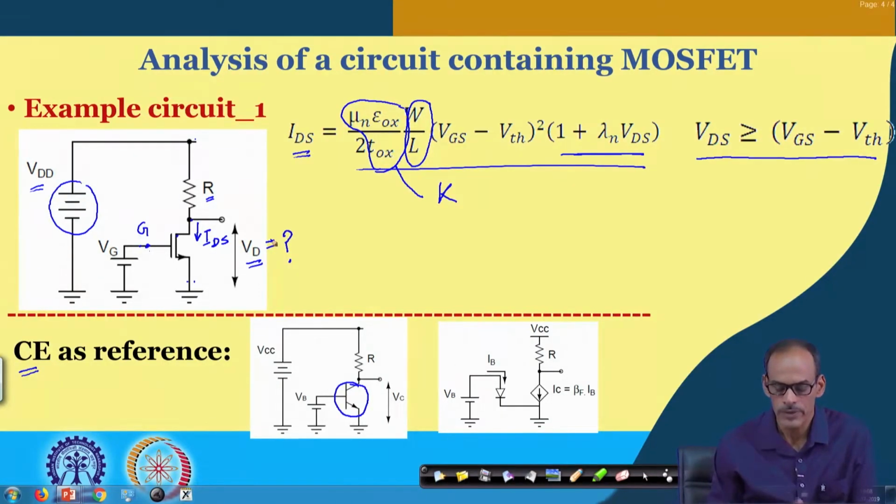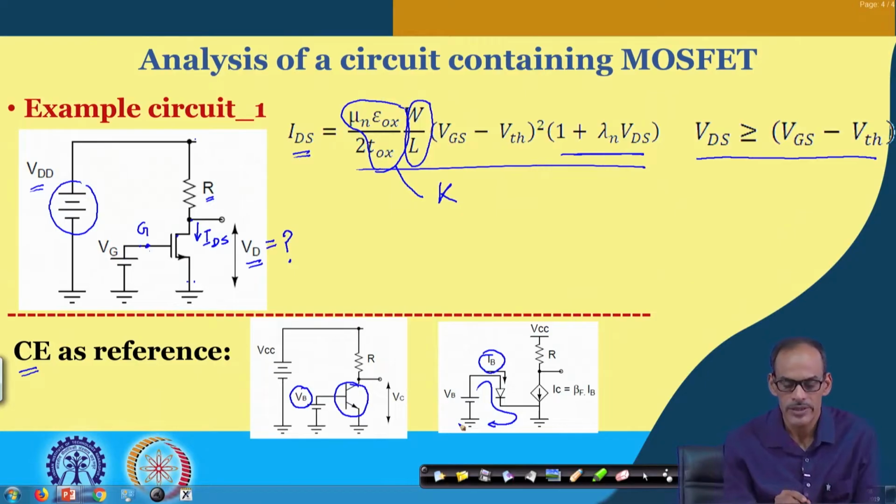or in this circuit incidentally that is the output voltage. So, if you compare the common emitter configuration, based on the bias condition at the base, we are suggesting to analyze the base loop to find the base current. Whereas, for this circuit, since the current is not flowing, of course, this model will not work, and of course, the dependency of this IDS on VG or VGS is different from the BJT circuit.